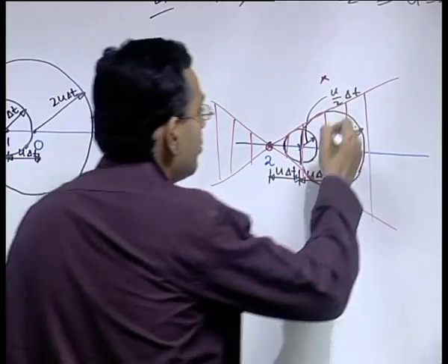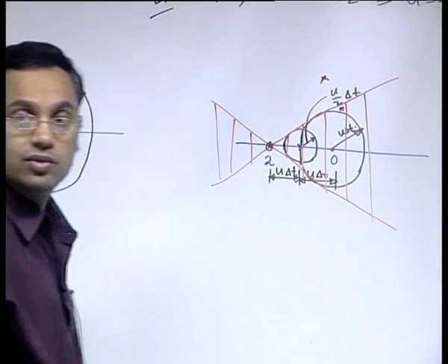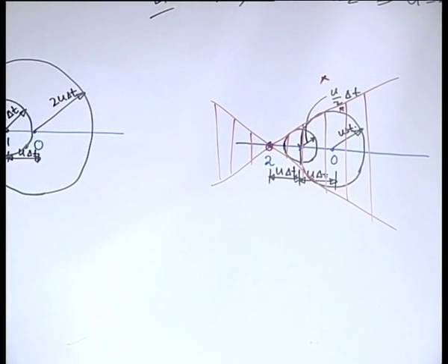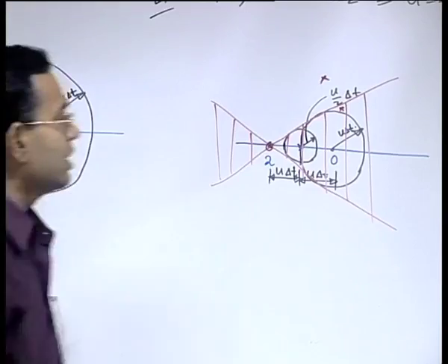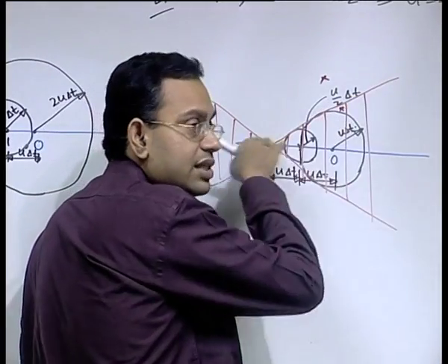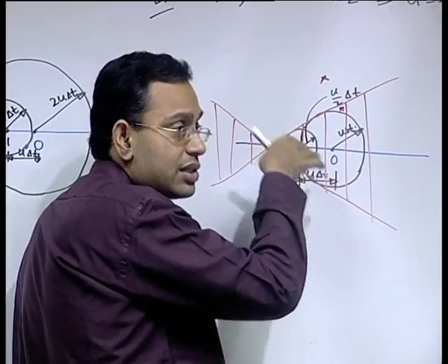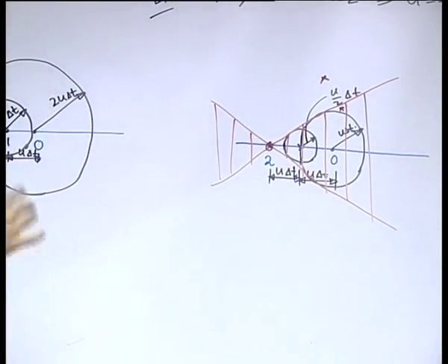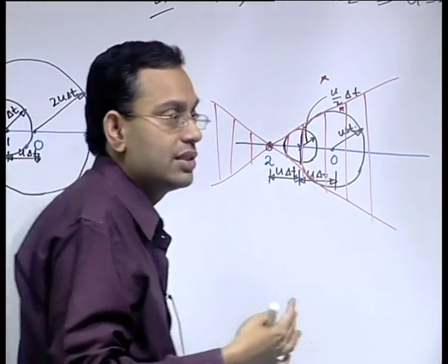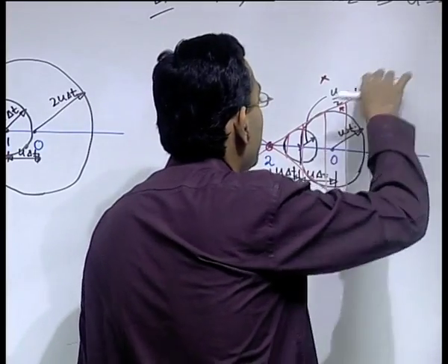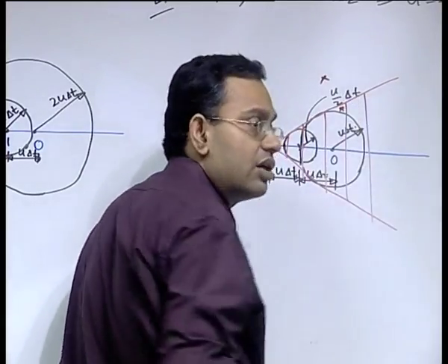But when the observer just enters this zone, will definitely feel the influence. So, there is some sort of discontinuity across these. Discontinuities of what? Discontinuities of actually the second order partial derivatives of phi. These are sort of weak discontinuities, and these are the characteristic lines across which these discontinuities are there.